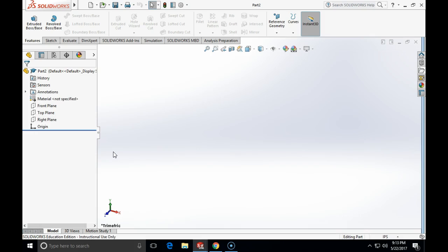So it's not something that is so obvious, because on your screen in CAD, if you make a hole of, let's say, 16 millimeters, or a 10 millimeter hole, or if you draw the circle and do an extrude cut, it will look the same on the screen. However, every time you have a standard hole, you should use the Hole Wizard, because otherwise it does not have the association of being a hole.